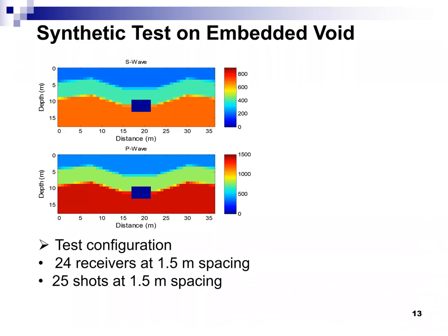When we're doing surface waves with hammers, we have different hammers because they generate different frequencies. And we want small hammers for high frequencies right near the surface.